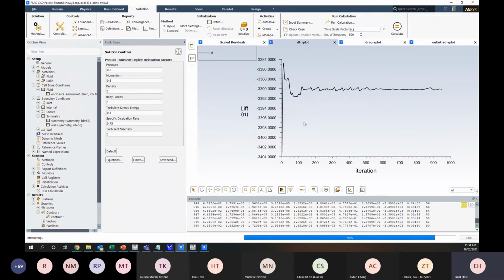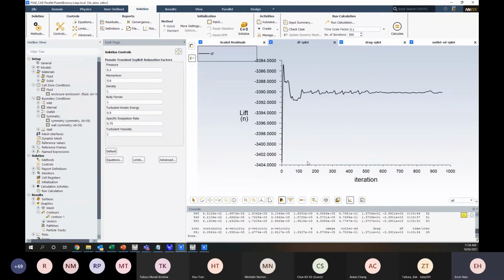Okay, so that's our near wall modeling. If you have any questions about near wall modeling, let me know. But suffice to say that getting our boundary layers, our inflation layers in the boundary layer, having a correct number of inflation layers and understanding what level of Y plus we're in for our first layer height is really important.